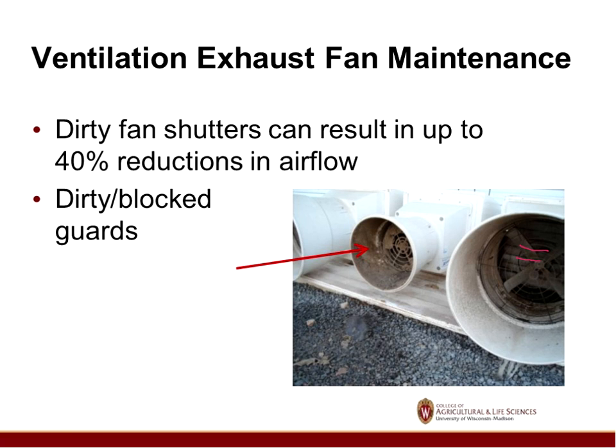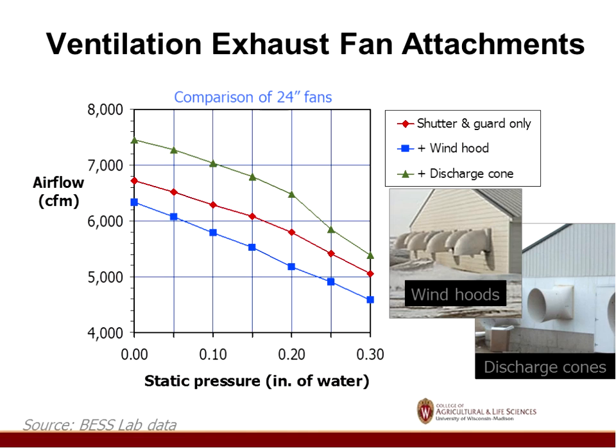The other is dirty shutters. Back in here, there's shutters or louvers, and if they're dirty, it doesn't allow the air to go through it, so that can reduce airflow. And the other is blockage on the guard itself. It's just like putting a board in front of it. But it needs to be cleaned. Now, the shutters or louvers, they can be cleaned and they can be lubricated, but they should be lubricated with a dry lubricant. If you use oil or grease, it's just going to attract dirt and make them stop working that much quicker.